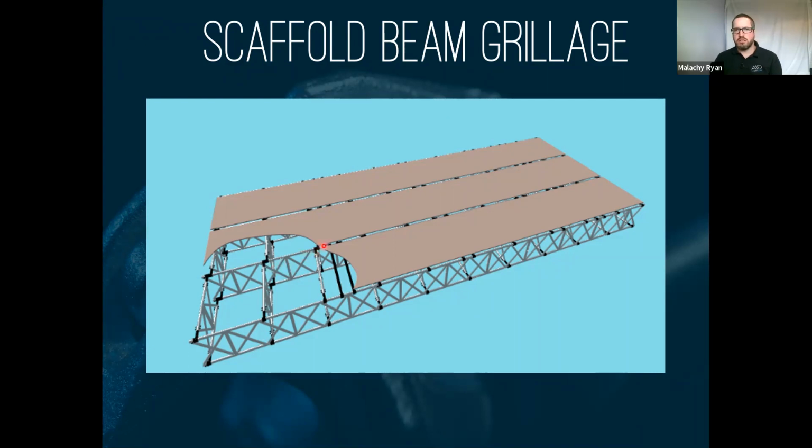And then you put a plywood covering over the entire structure. So the beauty of this is a lot of this can be prefabricated and brought to site ready to lift to the underside of the bridge. You could also prefabricate it on site at ground level and then just transport locally across the site to lift up into position. They are very versatile. You can create lots of different shapes to suit bridge piers and decks and that. And I'll just go through some of those in a moment.